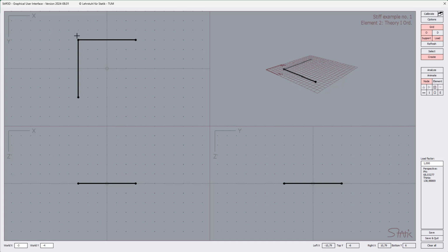You may ask, what was the selection for the z coordinate? Every node has 3 coordinates, x, y, and z. What was the automatic selection? This automatic selection is with respect to this hair cross, what you see here. I just selected the hair cross. And this hair cross, that's what we call the design node, gives us the missing coordinate if we are generating a node here in one of these views, x, y, and the others. So pressing here in the xy plane somewhere and generating a node creates a node with the z coordinate of the respective crosshair design node.